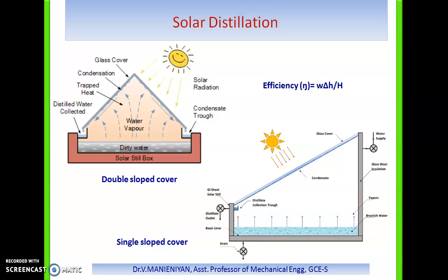The performance of the solar still is generally expressed as the quantity of water produced by each unit of basin area per day. This quantity will vary with the design of the solar still, the intensity of solar radiation, and the surrounding atmospheric conditions. The production rate depends primarily on the amount of solar radiation available, but is affected by other factors like ambient temperature, wind speed and atmospheric humidity.